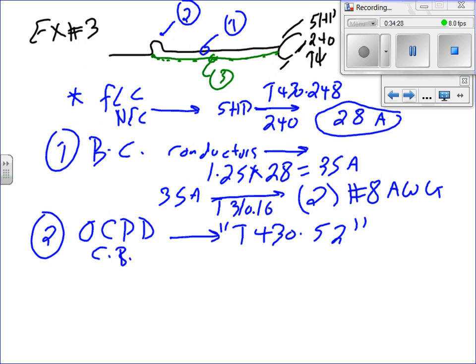Okay, everybody's at this table. I'm going to talk about this table in detail in a different chapter, but I want you to pay attention to two things right now. Number one, the last column. What does the last column say? It says inverse time circuit breaker. That's what we're going to be using. Why? Because I said so at this time. And the second thing, look at the first column. It says type of motors. What type of motor do we have? Single phase motor. Cross-reference single phase motors with the inverse time circuit breaker.